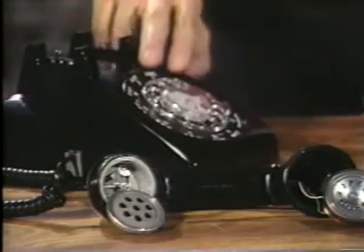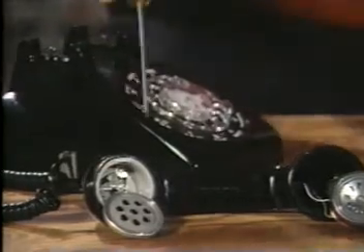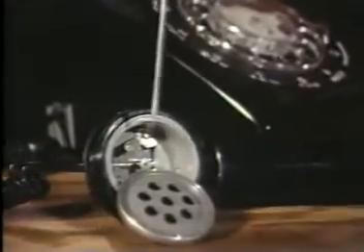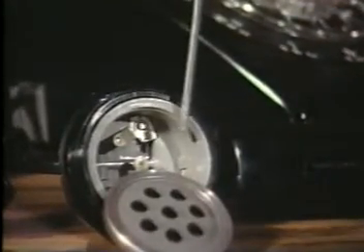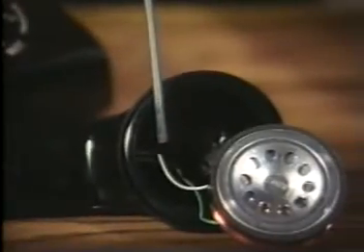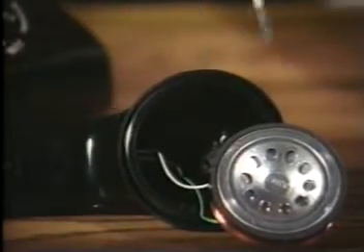There are millions of access lines throughout the distribution network. For economic reasons, these access lines are two-wire circuits. Although the telephone set itself is a two-wire instrument, the handset is a four-wire circuit with two contacts for the transmitter connection and two wires for the receiver connection.